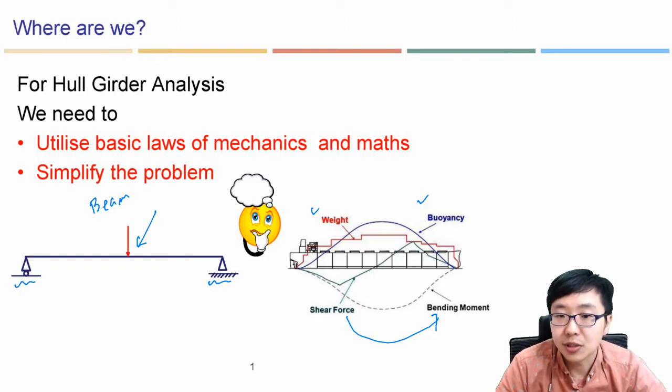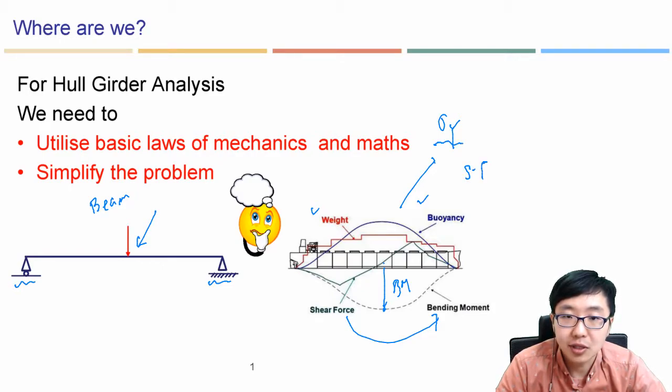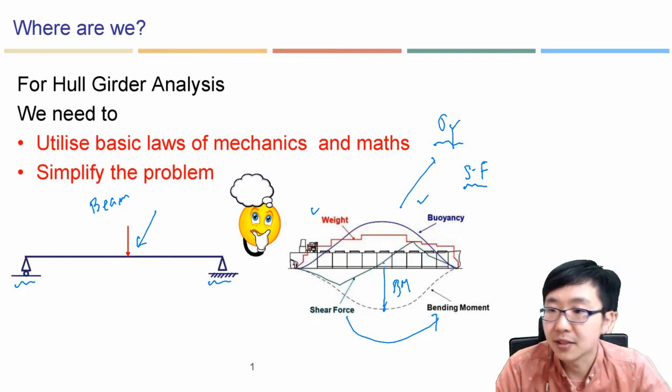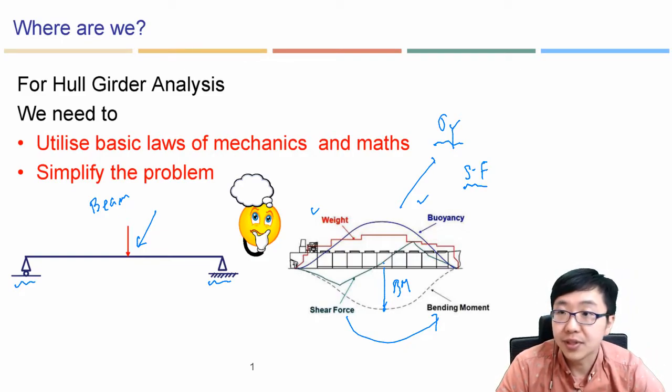And the next step was, from the obtained bending moment diagram, we could find the maximum bending moment, the position, and then we can calculate further. After that, we should be able to check the material yield stress or the capacity, so that we can compare those things and the material part, so that we could calculate the safety factor. That was the previous learning.